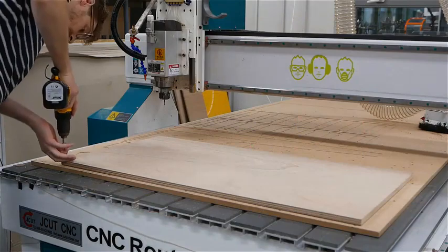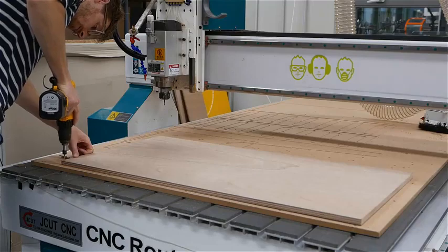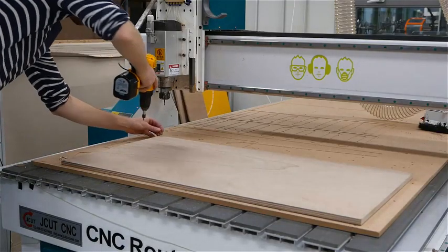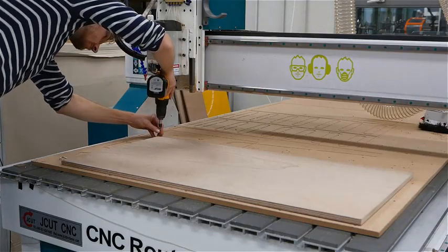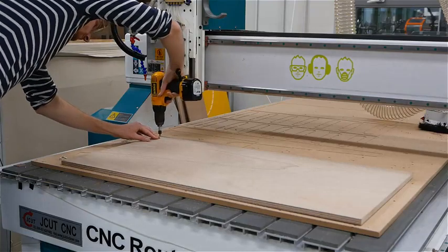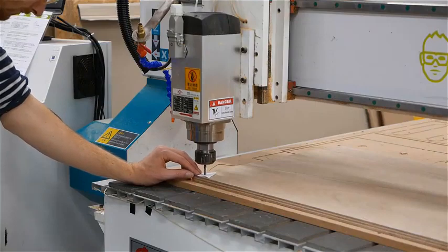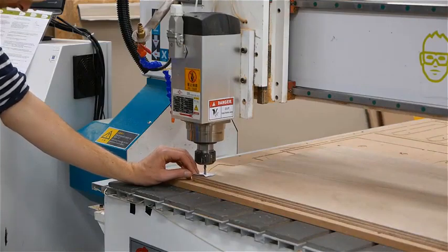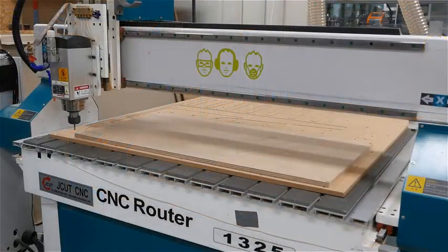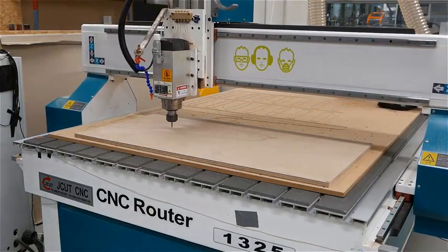The first thing to do is to fixture our slab of plywood on the machine. We did so by simply screwing it down onto the spoil board, using one screw for each of the 4 corners. The next step of the process is to set the 0 point on the top left front corner of the block. Here you can see the Z 0 being set. And then the milling process can be started. First the holes, then the outer contours.